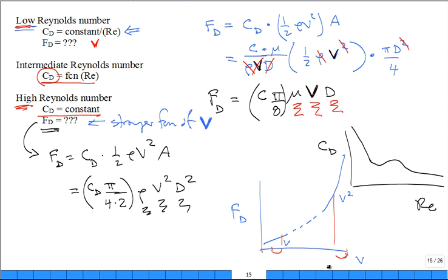If I wanted to double it, all I would do is take the new speed to be the square root of 2 times v, or 1.41 times v, right? I don't have to double the speed. Just a 40%, 41% increase somewhere in there. True? That I have doubled the speed. All right. I mean, doubled the drag force.